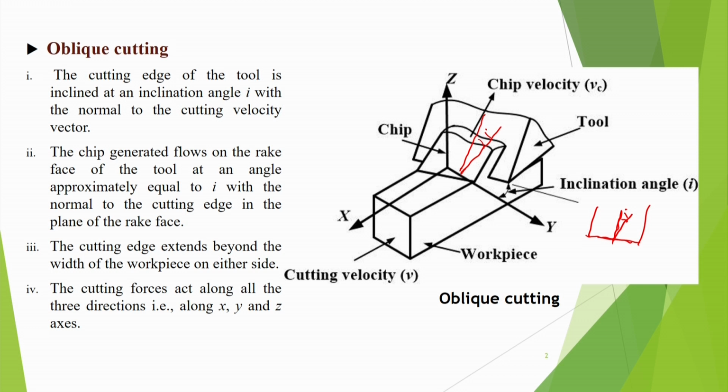The cutting edge extends beyond the width of the workpiece on either side, which we are assuming here so that we can understand that it is only shearing action. Cutting forces act along all three directions, that is along the x, y and z axes. The x direction is called the cutting force or power producing force, and then there are forces along y and along z also.